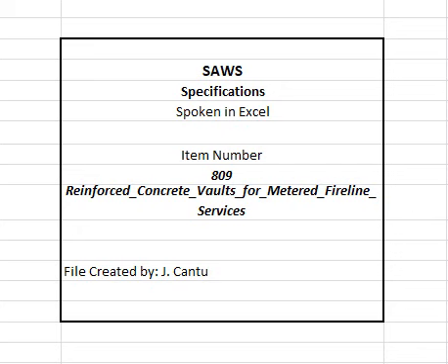E. ACI 308, Standard Practice for Curing Concrete. F. ACI 309R, Guide for Consolidation of Concrete. G. ACI 311, Guide for Concrete Plant Inspection and Field Testing of Ready-Mix Concrete. H. ACI 315, Details and Detailing of Concrete Reinforcement. I. ACI 318, Building Code Requirements for Reinforced Concrete and Commentary. J. ACI 544, Guide for Specifying, Mixing, Placing, and Finishing Steel Fiber Reinforced Concrete.